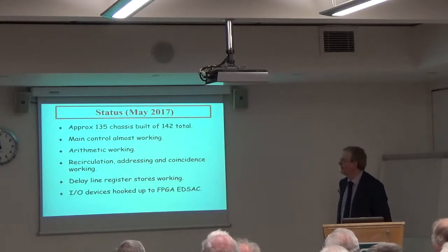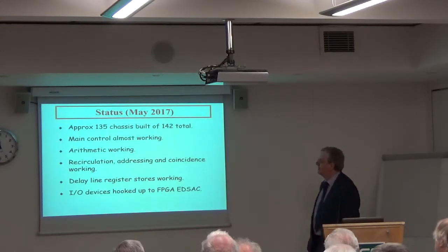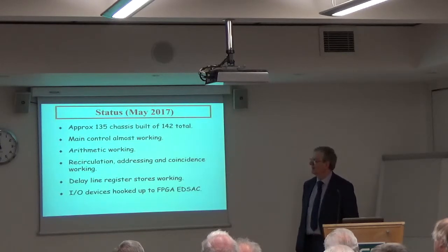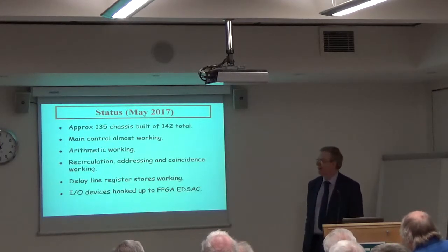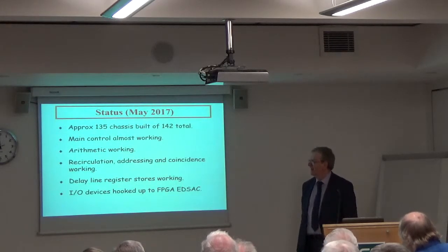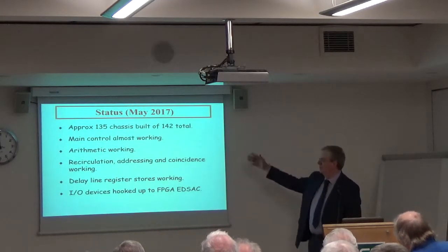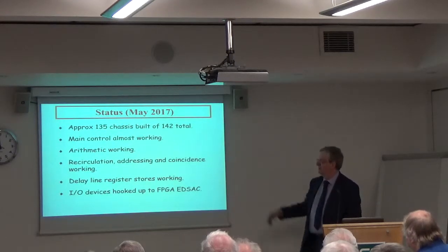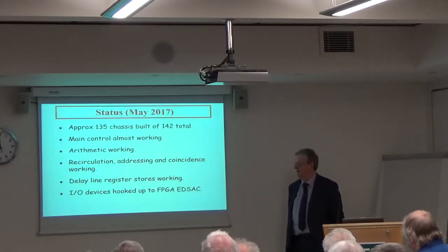So, wrap up. Present status, we've built 135 of the total of 142 chassis required, and we understand the remaining 7. Main control is almost working. That's where the monostable that needs to be a bistable circuit held us back. Arithmetic is working. It was working in Cambridge. The guy who designed that built it all and tested it all in his workshop in Cambridge, and then we heaved it up to Bletchley Park, and hopefully it will be working again once we wire it back together. We know all the memory system is working. We know the delay line stalls for registers are working, and we've made the I/O devices work using an FPGA.